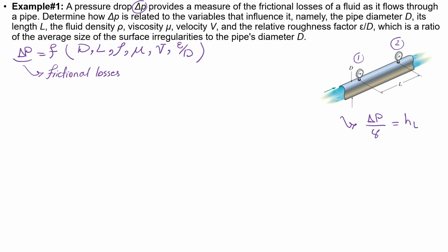Okay, so this should be very familiar to you. This is a dimensional analysis problem. Remember that the purpose of dimensional analysis is to find those pi terms, dimensionless groups that can relate different terms to each other, right? Okay, so what I'm going to do is, first of all, find the number of variables, and the number of variables is defined by n. The number of variables would be 1, 2, 3, 4, 5, 6, and 7. So I have 7 variables that are important in this phenomenon.